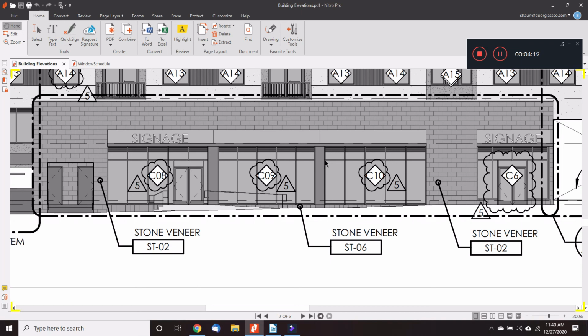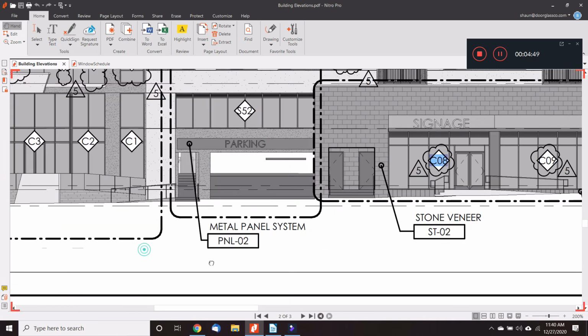So it may be important to measure these 3 openings relative to each other, not just the opening, but the relative height difference in the floor at this opening and this opening. If the floor slopes an inch and we only measure each opening and make the frame just for that, then it's possible that the horizontal elements don't align with one another.